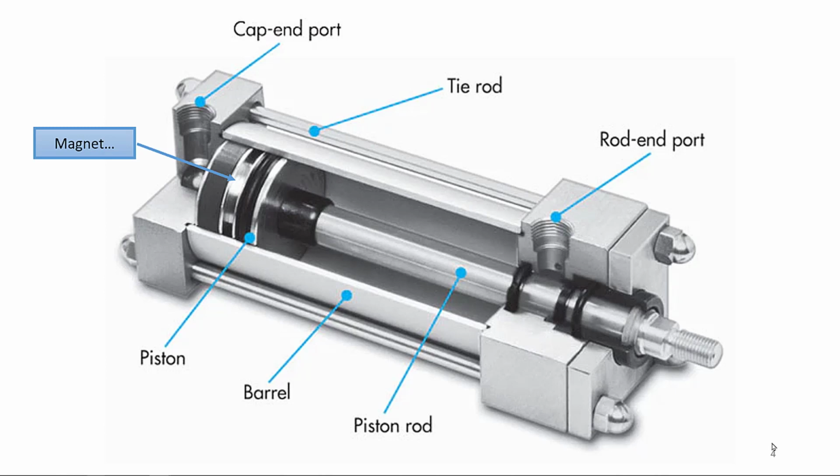But then when you retract it, notice that some of the surface has been reduced by where the piston rod attaches to the piston. Now let's say that's 1 square inch, thereabouts. That means you've got 2 square inches left of surface for 50 psi to push on. That means it's going to retract at 100 pounds force. It extends at 150, retracts at 100. That's just something to keep in mind, folks.